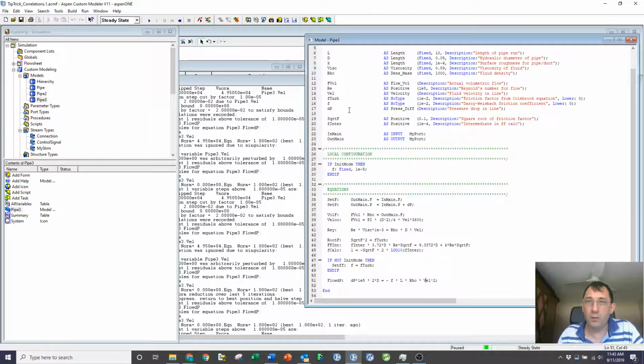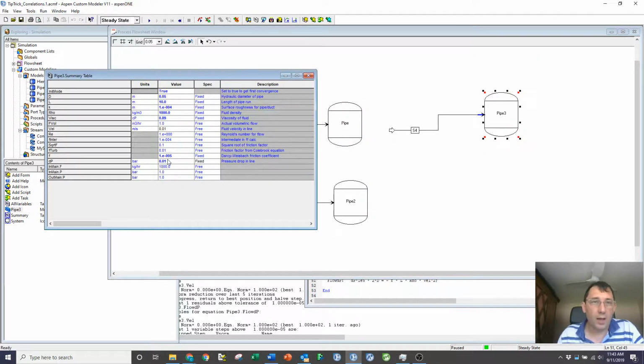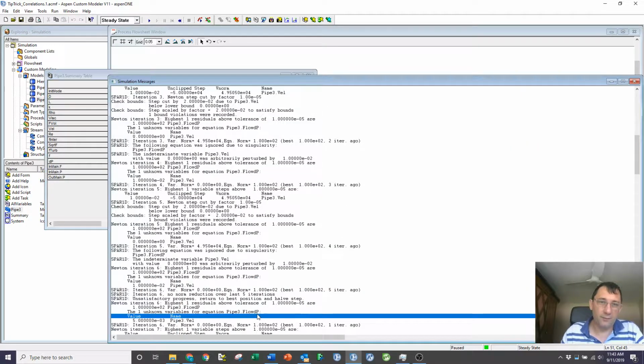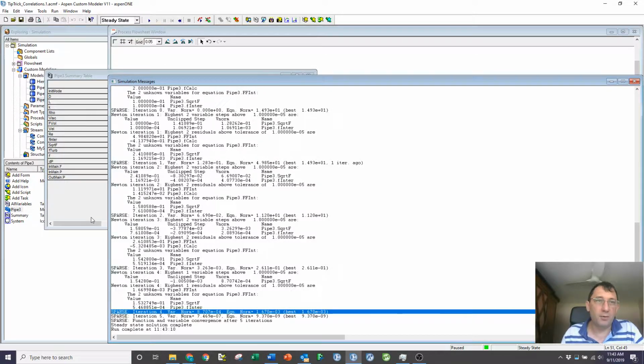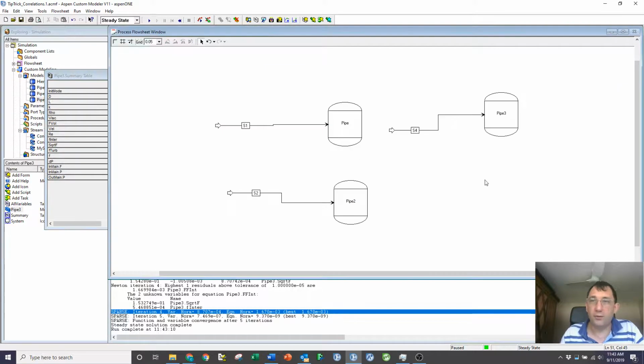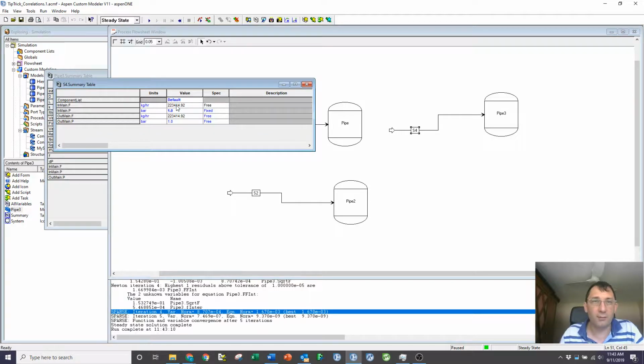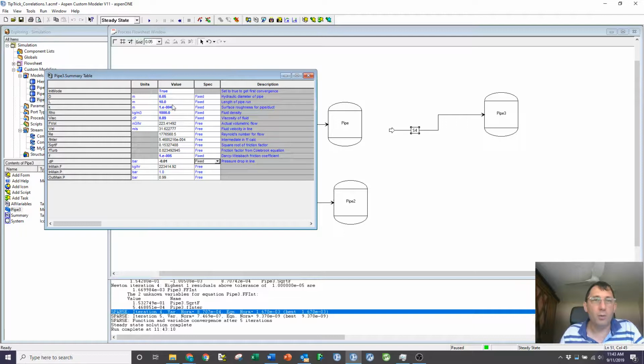and so really what I want to do is come into the system and have it have a pressure drop of minus 0.01. And if I then do that, then of course it converges nicely and gives me reasonable solutions. I've got an enormous flow rate through the system. Instead of 1,000, I've got 200,000 kilos now, so I've got a relatively big pressure drop with a relatively low resistance. But nonetheless, it's converging and it's working well.